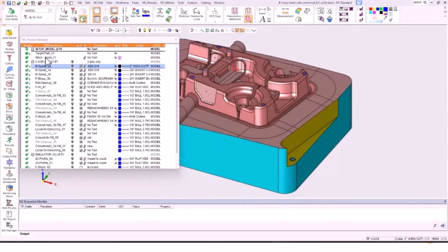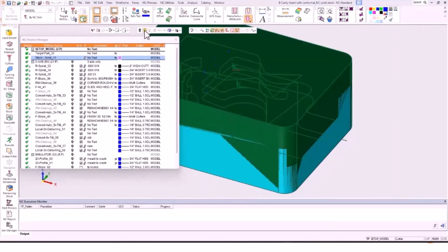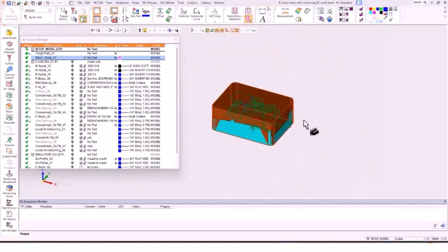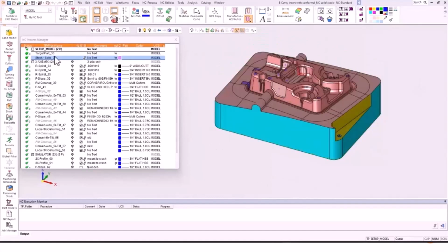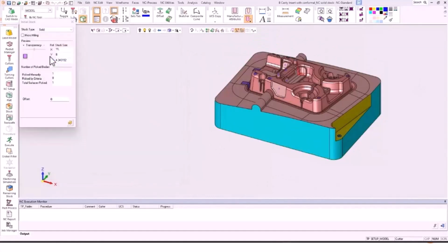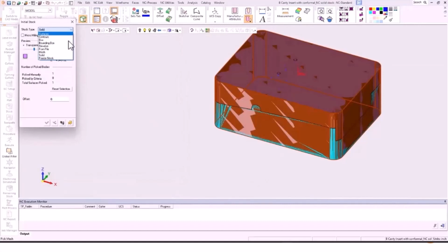When I created this toolpath, I had created a solid stock. The solid object is right here. It was a simple extrude up from the bottom of the block to replicate what might have happened in a previous operation. The stock object itself comes from the drop-down stock. I have the option to add an offset. This stock is more accurate than stock by surfaces.